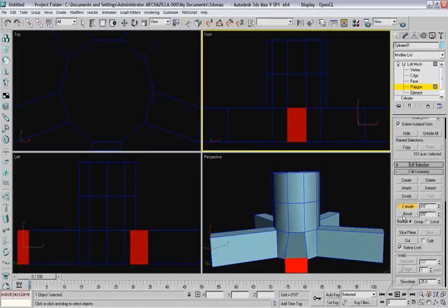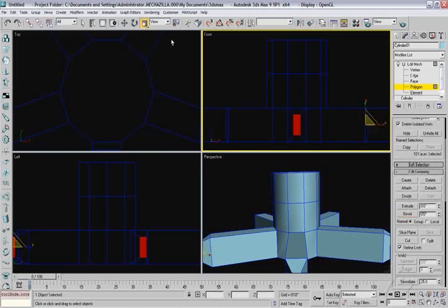If you look at the bottom of most of these legs, they tend to curve at the end, so we're going to use our bevel tool next. With the same 5 selected, I'm going to go up to my front viewport, hold down my mouse button and push it forward just a little bit. And then I'm going to scale down those polygons quite a bit. That's a little much, so I'm going to use my scale tool again. Actually, just undo that and do it one more time.